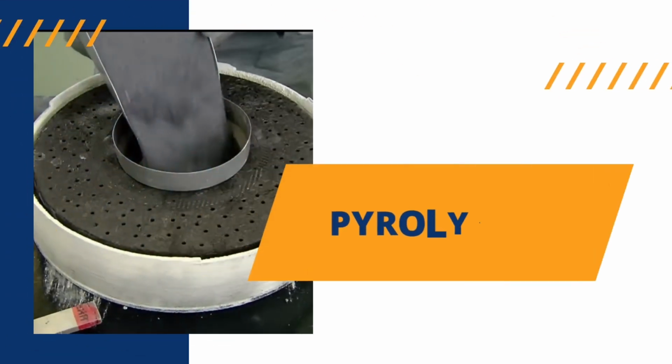The third step is pyrolysis. The serious business begins when the molded rotors are placed with other like parts in an oven with the ability to maintain an oxygen-free environment at high temperature. In addition to numerous rotors, a quantity of solid silicon is placed in the oven. Nitrogen is pumped in to displace the air and the temperature dial is set for 1000 degrees Celsius.